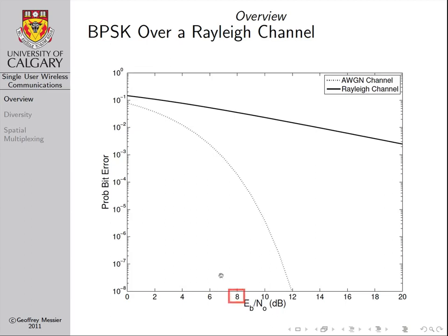So what you would then do is take that 8 dB, go up on this plot, determine what your bit error rate is, and use that as your system performance value. So basically, we don't include large-scale attenuation in our derivation. We assume that the system designer would add the large-scale attenuation later on when using these bit error rate plots to figure out what their average received signal to noise ratio is, and then what their average bit error rate would be.